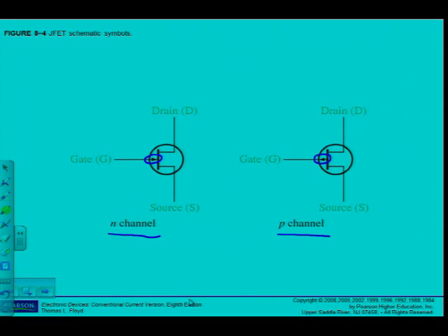And you have to remember that, because when you have to work with a circuit that's been given to you and have to do some calculations or draw some graphic analysis or whatever, which we will also discuss in sections to come, you have to know that you're working with an N channel or a P channel, otherwise you're going to do it totally wrong. So make sure that you do know the symbols for the JFET as well.